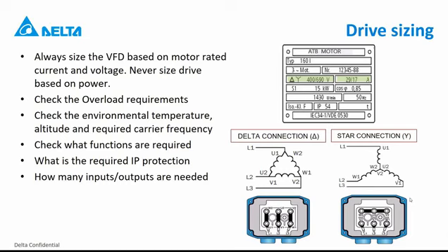You also need to check how many inputs and outputs the application needs, whether the drive actually has that, or if you need to use some I/O extension, or if it's maybe more convenient to use a different drive or just use an extension module.